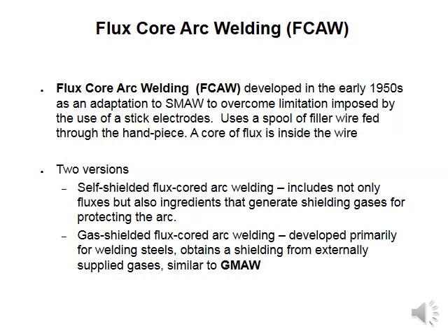So you can weld steels with this, but it uses a shielding gas like GMAW, and there's a flux on the inside of the wire. There's a zillion different kinds of dual shield, they call them. I think dual shield's a trademark name, but if you start talking to people and say, hey, I need a flux core that's dual shielded, they'll know what you mean. The people selling the welding wire are going to know that you need a flux-cored wire that also needs a gas. And there's a lot of these wires that can go both ways. So there are two different versions of flux-cored arc welding.